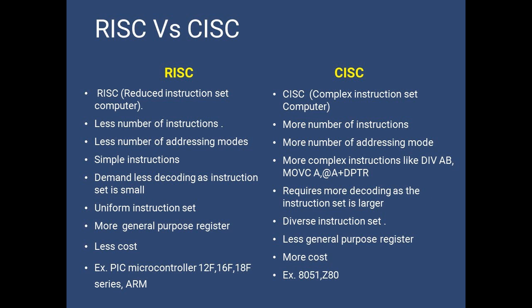Now, all the controllers that we have seen so far, all PIC microcontrollers, come under the RISC series, that is reduced instruction set computers. Controllers like the 8051 or Z80, or if we take an example of a processor which we have learned, the 8085, are complex instruction set computers. So this was a brief comparison between RISC and CISC terminologies, which are used in microcontroller or microprocessor design.